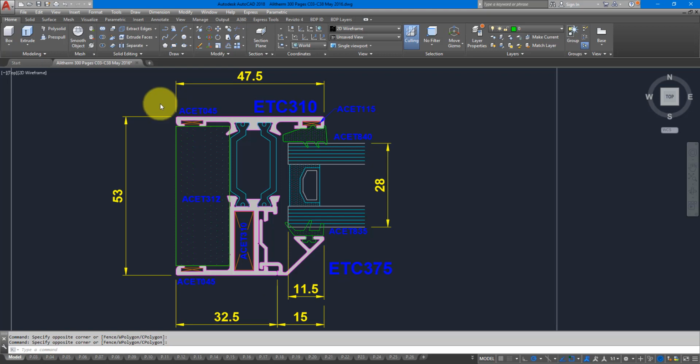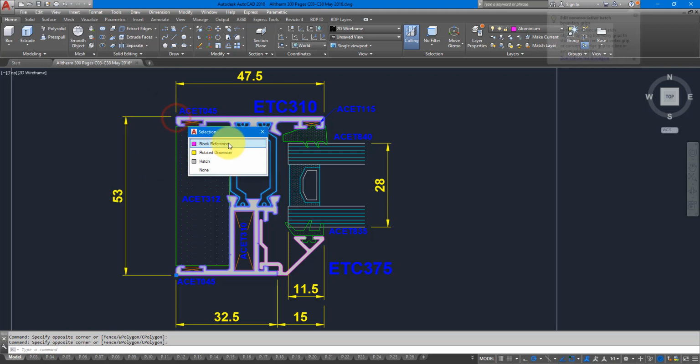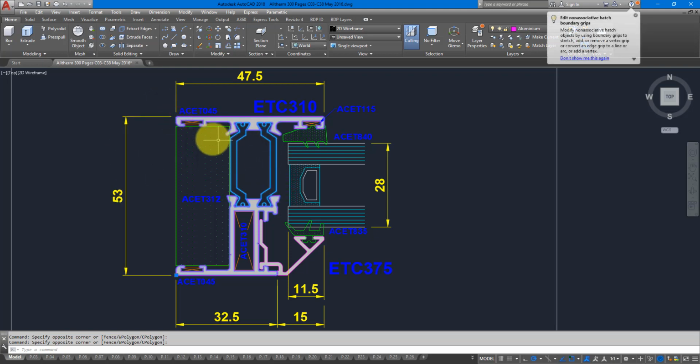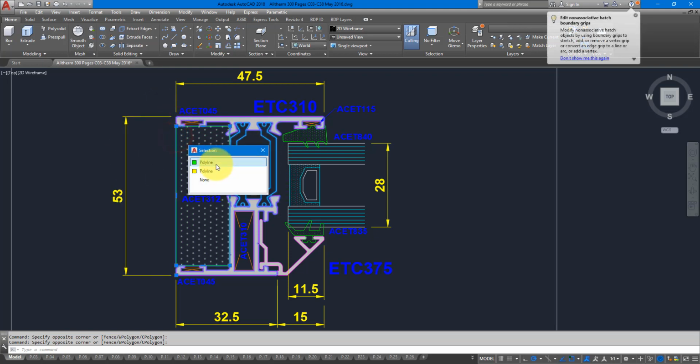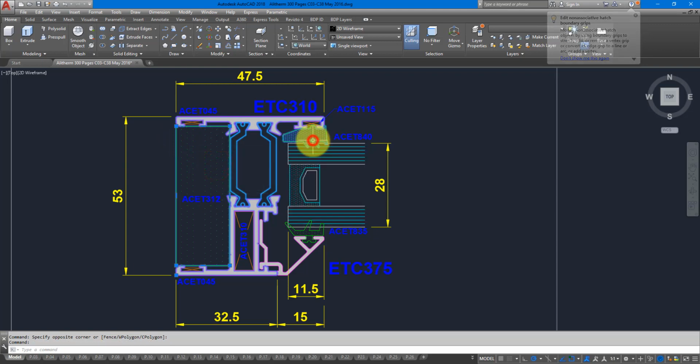We can now select everything you want to bring into Revit. So maybe this block there, this one as well, another one here, this detail item. Let's include the section of this glazing here as well, so we can reference this later in Revit to make our glass panels. Alright, for now that's all I need.